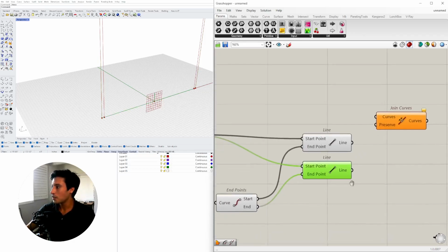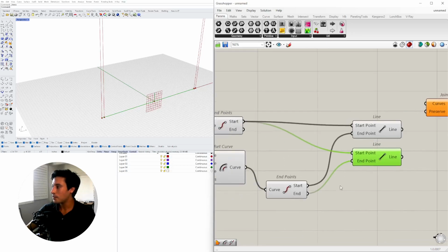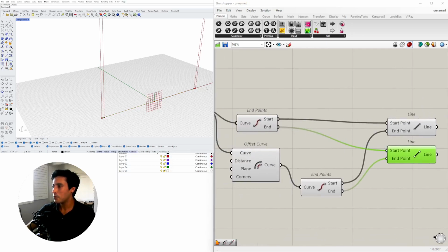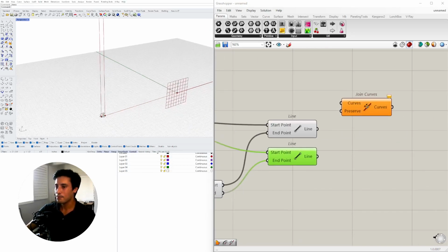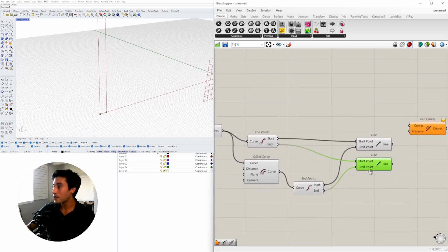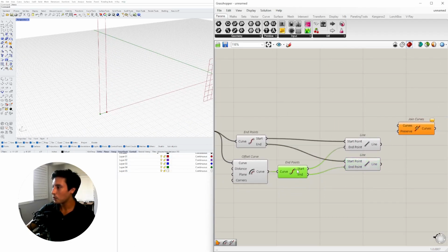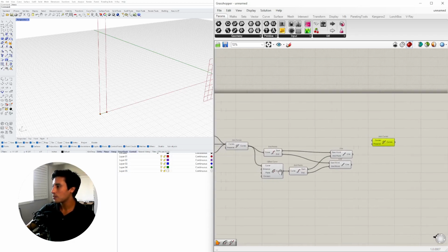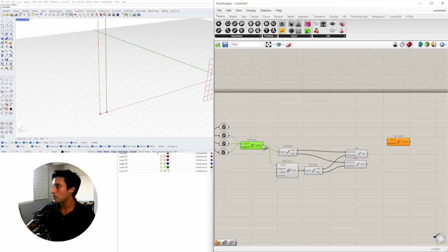And we'll be joining, not this, because here's what happened. I went from end to end point, and that messed us up. So what happens is I wasn't careful enough. Sometimes I try to go a little quick here to save some time, but endpoint creates this line. Start point and start point creates this line. So what I had was an issue there. And we'll take this, hold down shift, same thing here, and these two.